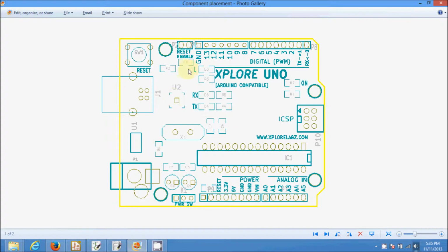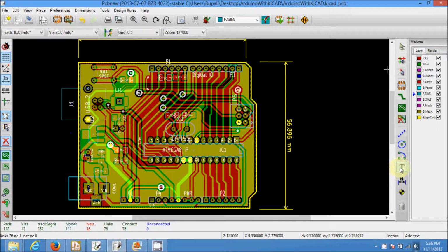Now in the picture that you see here, this was designed earlier, and these are all the labels required for UNO. So it names the digital pins 0 to 13 and analog pins A0 to A5 and all the power pins, and also a derived name, which could be anything as you wish, and some other labels such as the website and the ISP connector. So I'll show you how you can put a few, and then you can put the remaining. So let's put the A0 to A6.